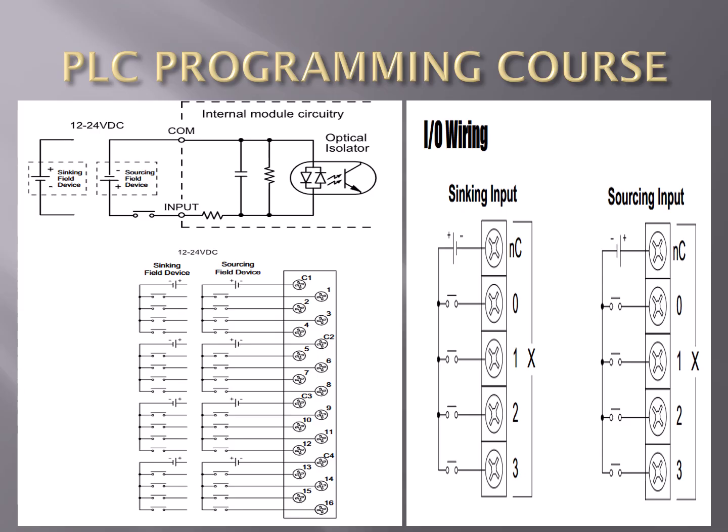And the opposite of that is the positive on the internal devices, plus voltage, and we're looking to sync that voltage down to 0 volts with a syncing field device. But that's actually called a sourcing input because the current flows in the opposite direction.